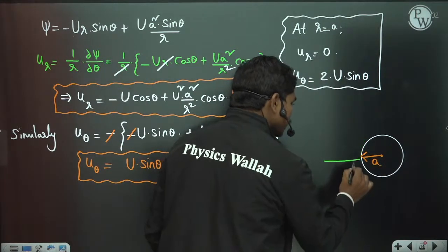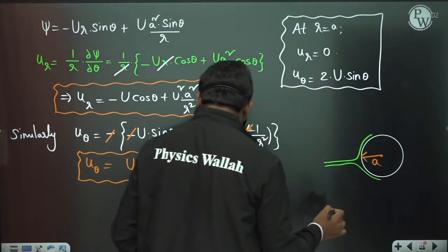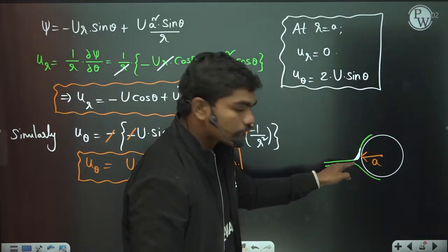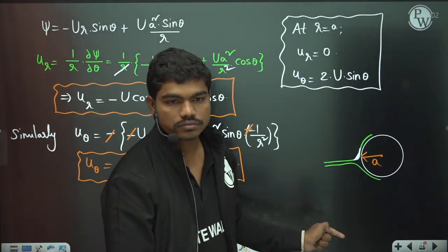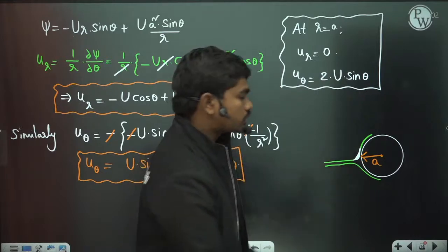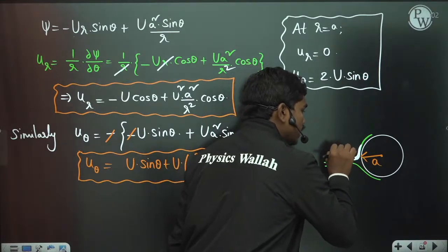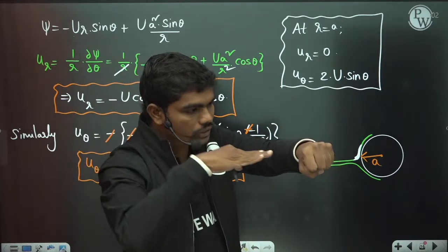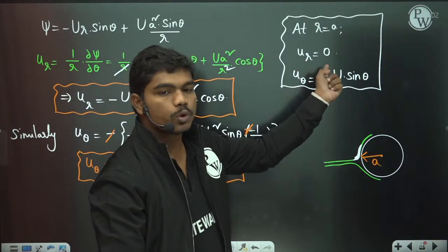location it takes a curvature, correct? So at this location, when the fluid particle is coming like this, definitely it takes a curvature like this. Means there is a certain amount of fluid which will try to rotate at this radius. Now tell me, at this location, is there any fluid which is actually going like this? Is there any fluid which is going radially at this location? Of course, some fluid is taking the rotation along the cylinder. But now tell me, is there any fluid which is actually going into the cylinder? Practically, is this possible? No, there is a thick cylinder which is blocking the flow. So whenever the fluid is coming, it slowly gets diverged around it. Okay, so radially there is no flow. So that's why clearly you can understand ur becomes 0 in this case.